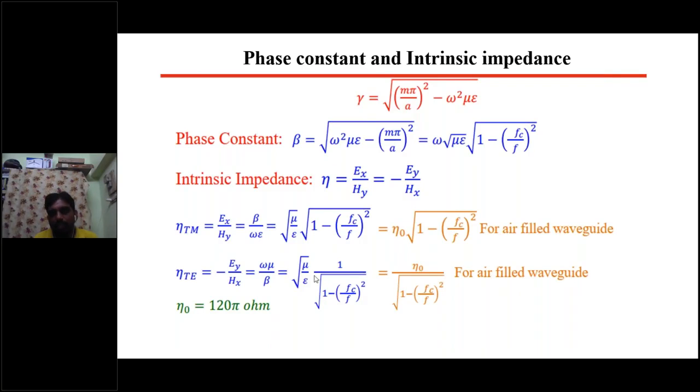These are all the parameters. We can expect one essay question from these waveguide parameters. A problem can be given like this: a rectangular waveguide has dimensions of 7.5 by 3 centimeters and is operated in the dominant mode. Find the cutoff wavelength, guided wavelength, phase velocity, group velocity, and wave impedance. We can expect this question 100% from this unit, as an essay question from either A bit or B bit.